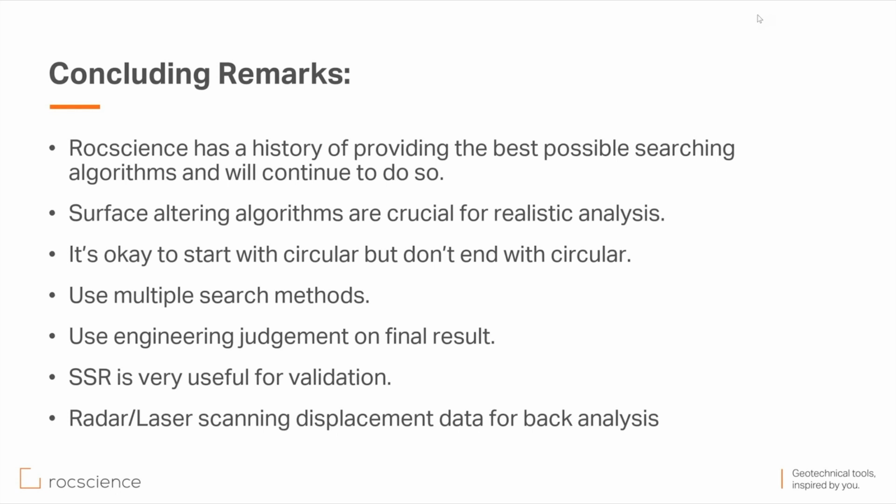And this can allow you to easily back analyze what your properties are, where the location of the global minimum is, and the size of the failure. So now we're getting into that realm where we can take data from field measurement, such as LiDAR, radar, and actually incorporate it into our analysis to make sure that our results are accurate. And that sort of completes the webinar.